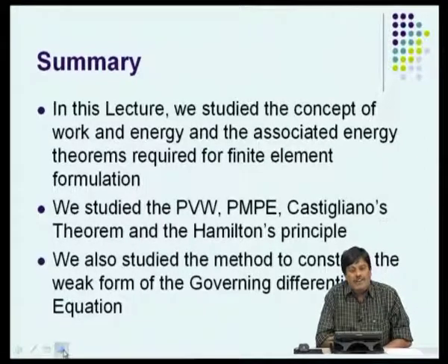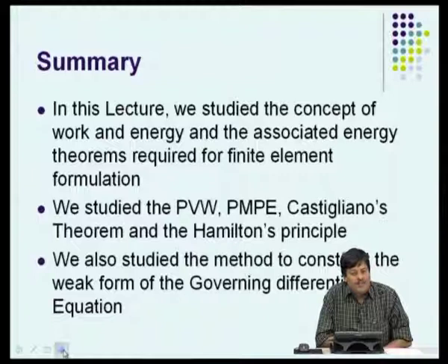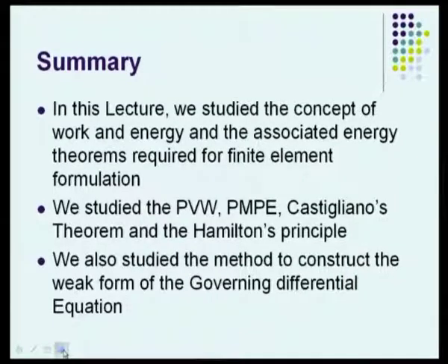We studied in detail the principle of virtual work, principle of minimum potential energy, Castigliano's theorem, Hamilton's principle, and said how they are linked to FEM. We also studied the method to construct the weak form of the governing equation for a given differential equation. We also studied some aspects of the calculus of variations and how we can actually construct the functional, and what restrictions the differential operator should have in order to have a functional.